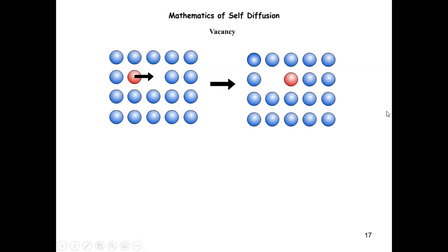And if you think about what other possible things can diffuse around in a solid state, we talk about interstitials, which is quite natural, as there are many alloys that are of this type. And the other, I would say most commonly seen diffusion, will be either called self-diffusion or substitutional diffusion, right? Now, in interstitial diffusion, you have these atoms sitting in the interstitials, and they move around, hopping into nearby sites by squeezing through a densely packed pair of the parent atoms in the parent lattice.